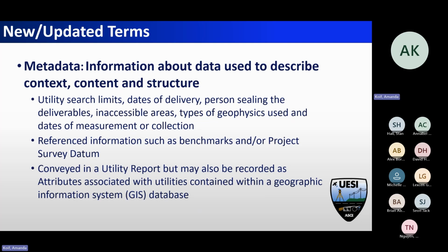They capture a lot of different feature codes, and in those feature codes, there's a lot of data that's associated with each one of those pieces of information. It's the size, the installation, the contractor that put it in, material. I mean, everything that you could ever want to know, there's a feature code that can be added. And now with OpenRoads, you can add all that data in there and start capturing that. And that information can be used so that instead of having all those leaders and lines all over your drawing, you can hover over a line and get all the information that you need from that, so that those notes aren't stripped away, and you can use the data pretty smoothly.